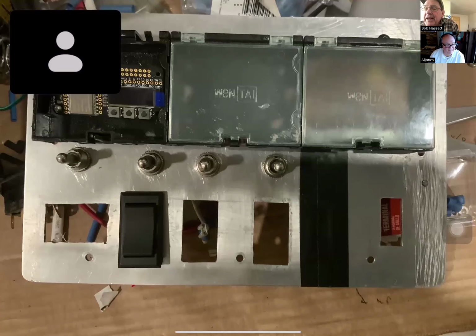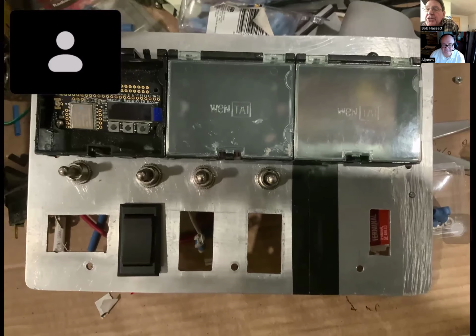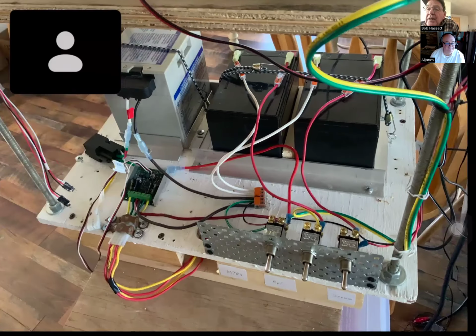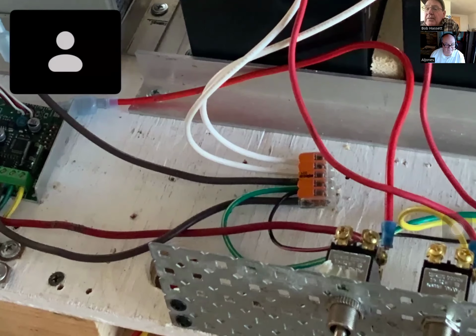But anyway, I cannibalized the 3 toggle switches and put them in there. I had some parts left over from some previous stuff, bolted that down. And I kept remembering that one should always tie all the grounds together. So right in the middle is that lock nut. All the grounds from the batteries and boards are coming into that.